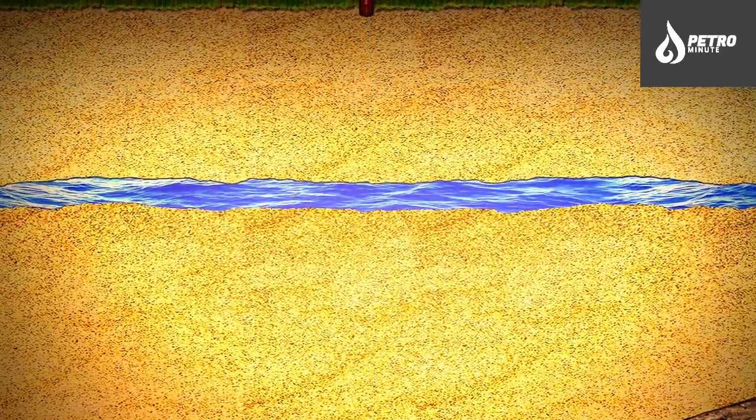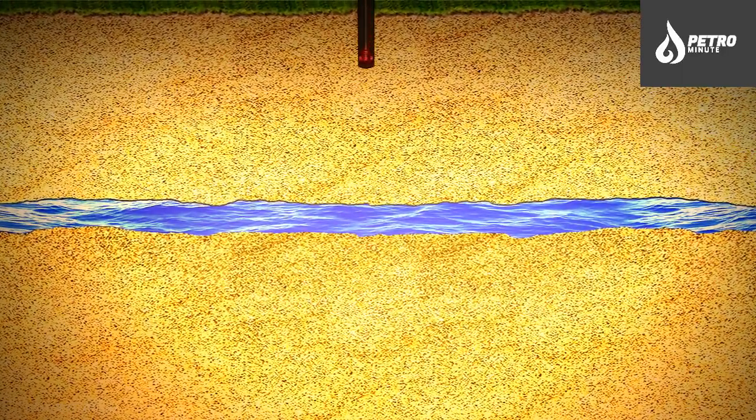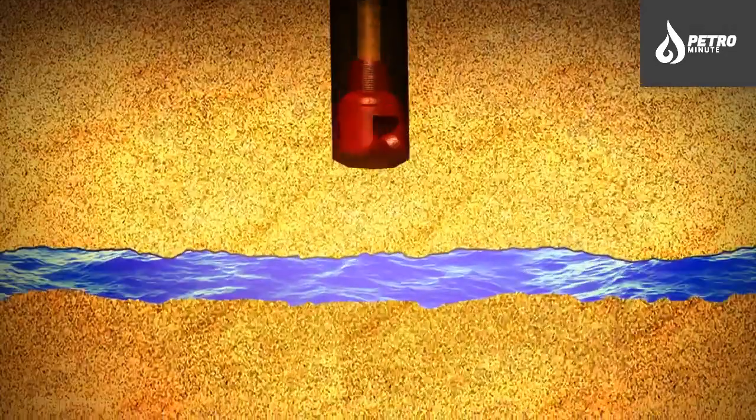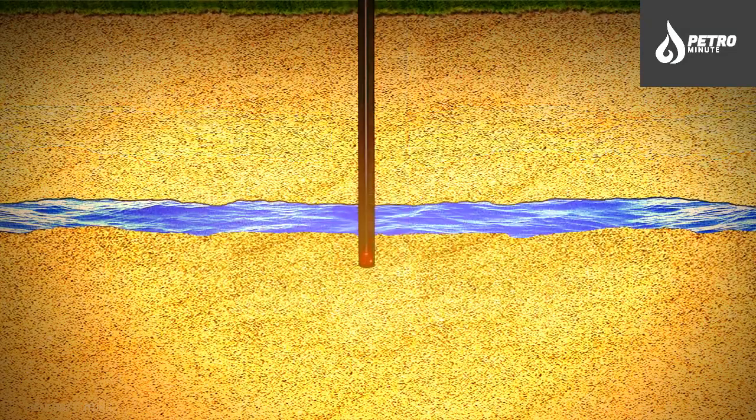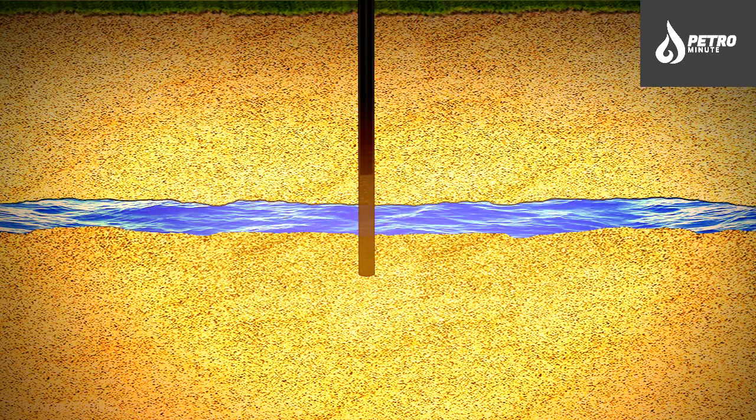A vertical hole is drilled to a depth below freshwater aquifers. Drilling mud pumped into the borehole cools and lubricates the bit and helps wash cuttings to the surface. This mud also coats the walls of the borehole, preventing mud from leaking into the surrounding rocks or water table. The drill bit is removed, and a steel tube called surface casing is inserted into the hole and surrounded by cement. This permanently shields the aquifer from contamination by drilling fluids or produced gas.